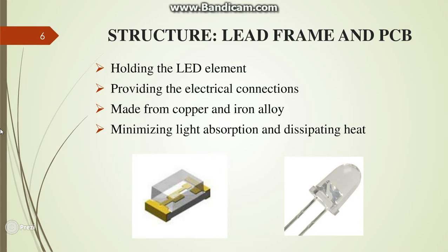Moving to the second component, the lead frame and PCB. Here you can see the lead frame and here is the PCB. These components hold the LED element and provide the electrical connection to the element from an external power supply. It's made from a copper and iron alloy. Highly reflective materials are used as the substrate material to minimize light absorption. Lead frame and PCB also play an important role in dissipating heat from the LED element.